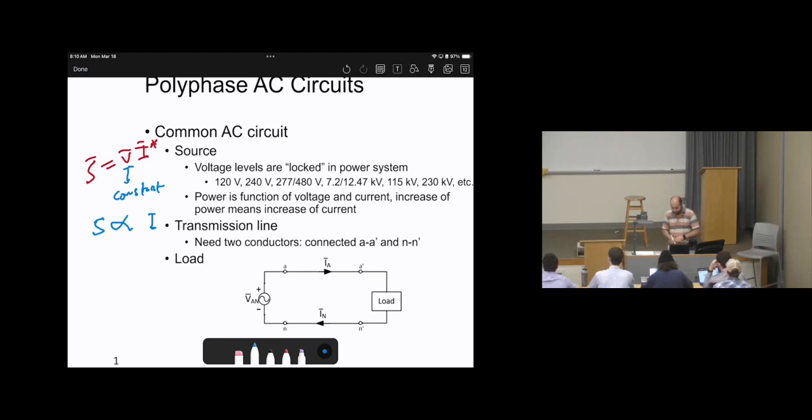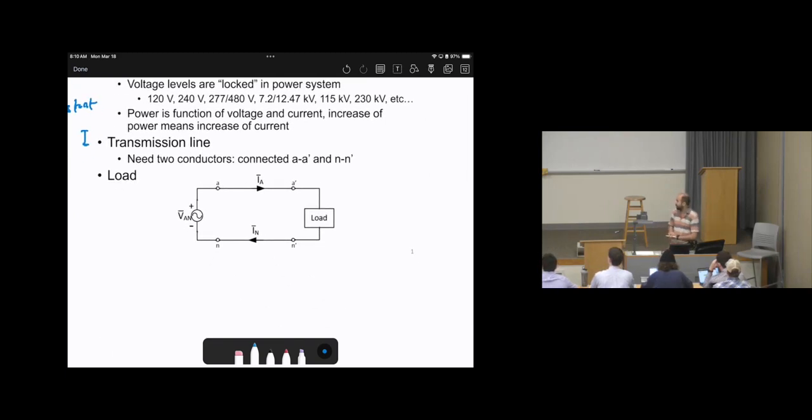So let's assume we have two conductors this way. We have the phase or voltage source connected to the load. Then we have two conductors, live and neutral, as we see in this diagram. And assuming the ampere capacity, where again S is directly proportional to I, let's assume that after doing several calculations, these conductors can supply only 1 kilowatt, as a rough number. So for this system, the maximum power that we can get is 1 kilowatt.